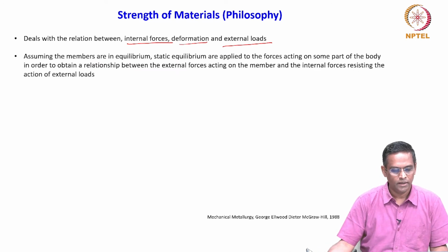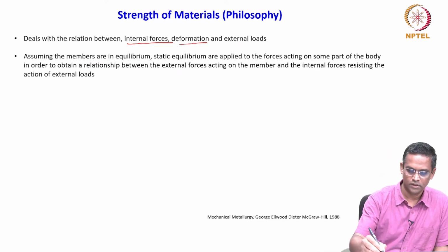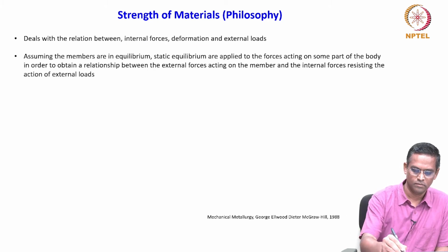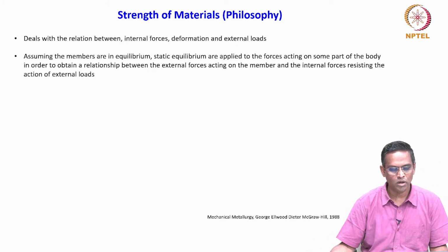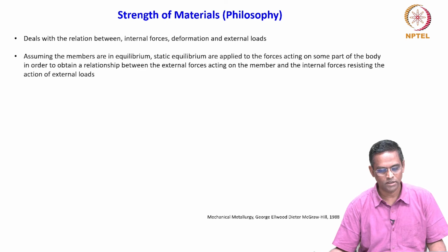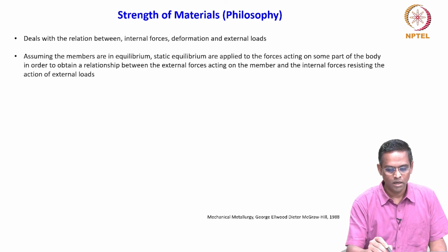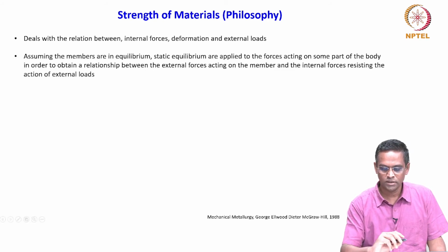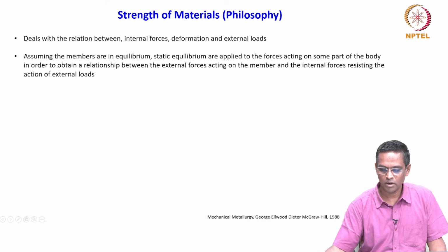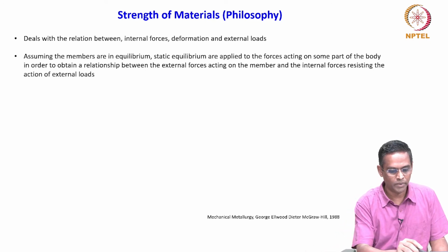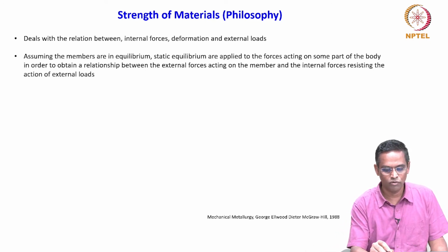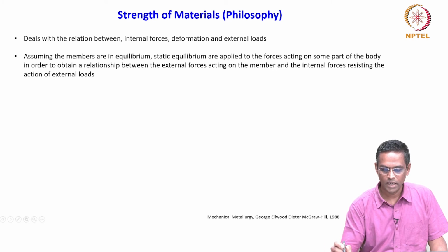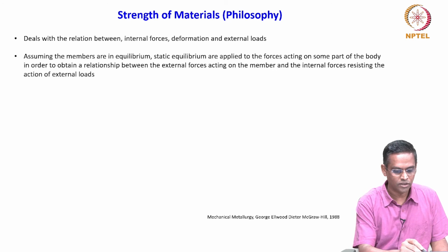So assuming the members are in equilibrium, that is static equilibrium, the equations from static equilibrium are applied to forces acting on some part of the body in order to obtain a relationship between external forces acting on the member and the internal forces resisting the action of external loads.